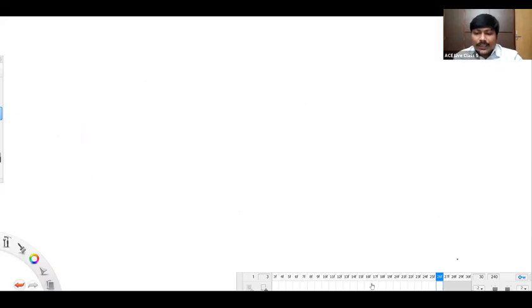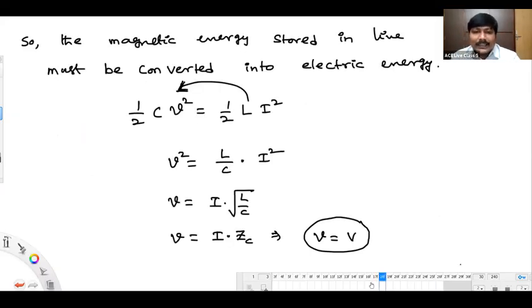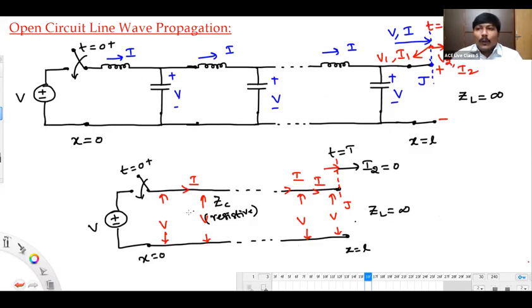It's a switching over voltage. We are doing a switching transient study only. Why are we going to call this a switching transient study? Because we are keeping a switch here? No, because of the voltage source. Practically speaking, the source in the power system network will be a voltage source only. That's why we call this a switching transient study.